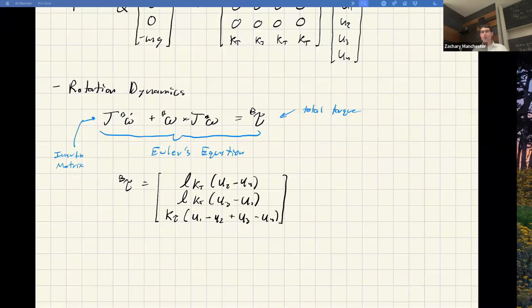Okay, so that's the full 3D quadrotor dynamics. This is the standard model, basically used in any kind of quadrotor sim and in pretty much any kind of quadrotor controller, unless you're doing something really crazy, next level, like crazy racing or aerobatic stuff. In those cases, people do more detailed prop modeling, more detailed aerodynamic modeling, and the latest stuff from folks doing drone racing and stuff like that.